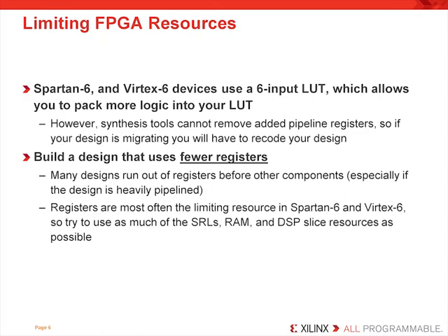This is because the LUT6 is again 40% more efficient than a LUT4, but this won't yield a performance benefit if your design only uses a couple of LUTs with 4 inputs, like a design that would be migrated from a previous architecture might only require.